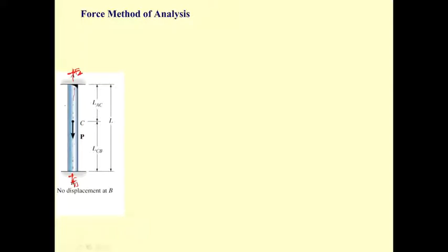This one has one degree of indeterminacy, and the degree of indeterminacy gives the unknown force. It's up to you: you may use F sub A or F sub B as the unknown force, and we call this unknown force the redundant